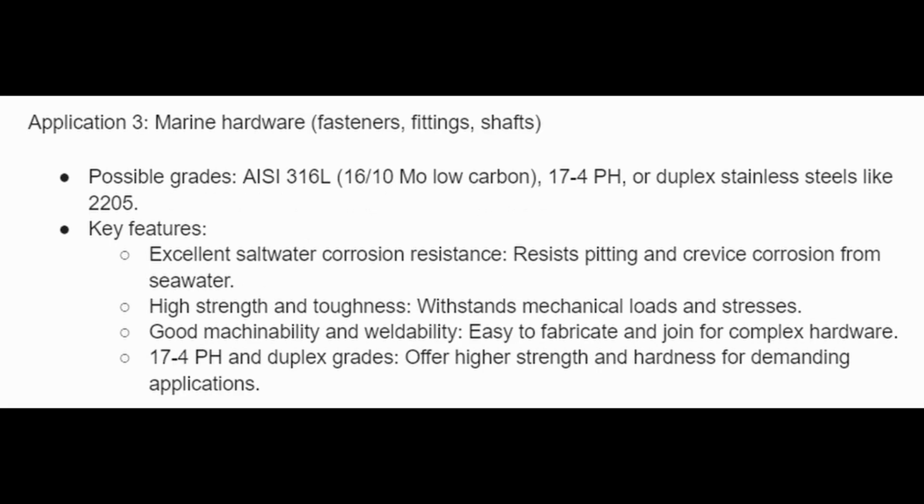Application 3. Marine hardware. Fasteners, fittings, and shafts. Possible grades 316 or even duplex, for example 2205. Key features. Excellent saltwater corrosion resistance. Resists pitting and crevice corrosion